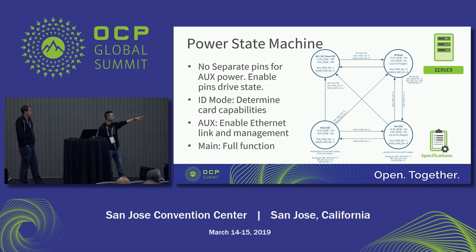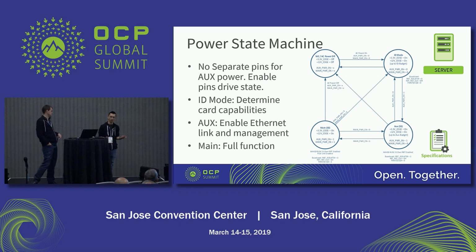The transition from aux power mode in the lower right-hand corner to the lower left is main power. That is accomplished via the assertion of main power enable, and here you have PCI Express reset deassertion. As previously mentioned in the timing diagrams that others have shown from the specification, that time is 1 second for burst. In main power enable, here you get the full operating envelope of up to 80 watts of power delivery, and depending on your system cooling capability, you may be limited from that.